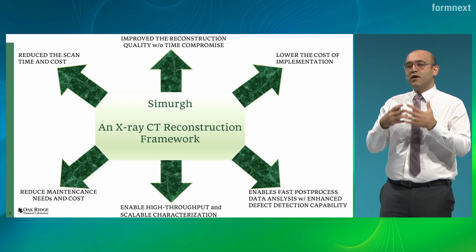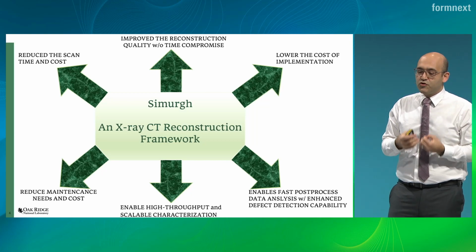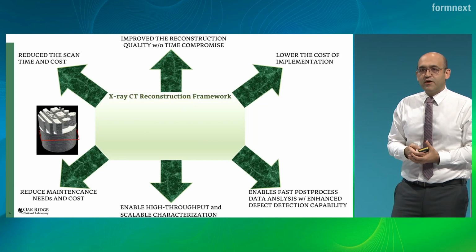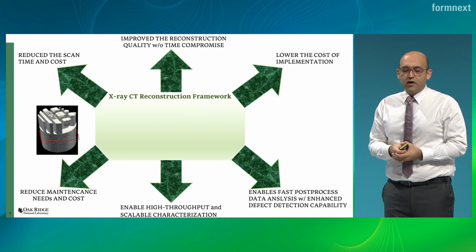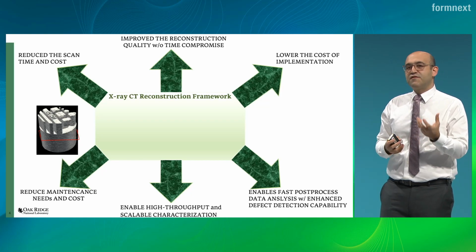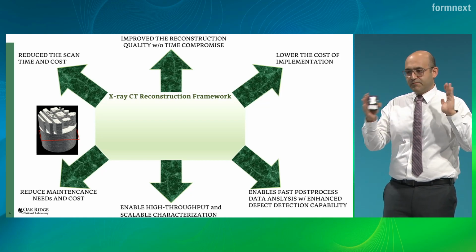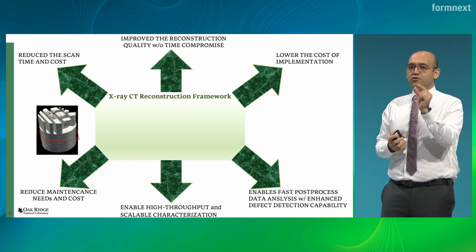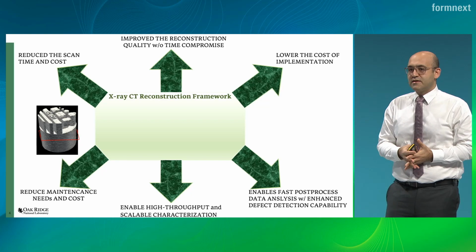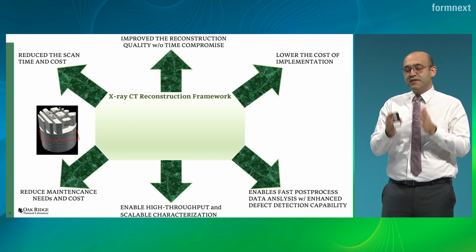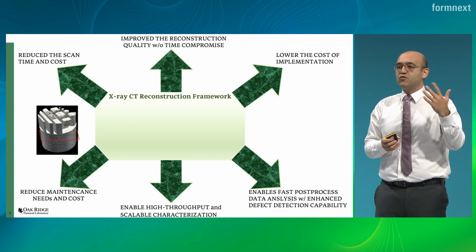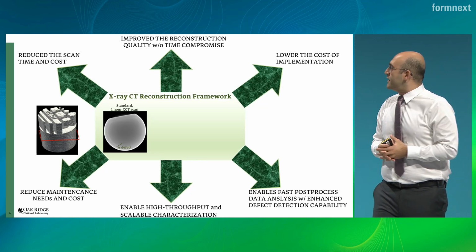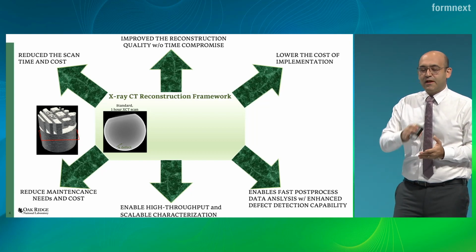Because of the high quality of the data, we have also enabled post-processing that is much easier to do with this data. Let me give you an example. Here, you are looking at the same geometry that I was talking about. This is 15mm steel. In most of the presentations that I have seen in the past few months or years at conferences, it's small cubes, 5-6 millimeters, that you see in the CT system. This is 15mm of a very dense part, which requires 1 to 2 hours of a scan on a high voltage CT. Let's assume here we have done a 1-hour scan on this sample